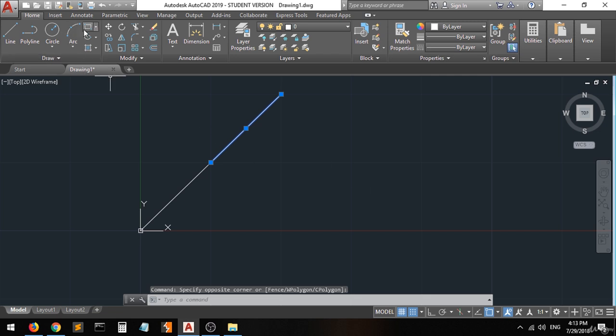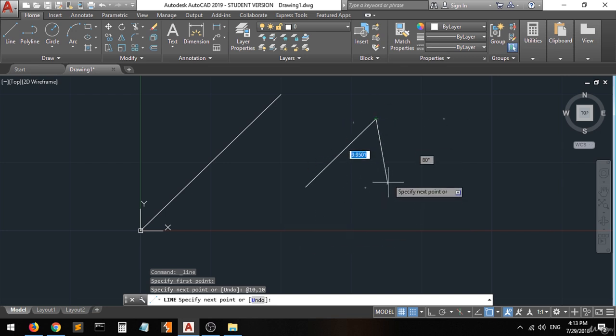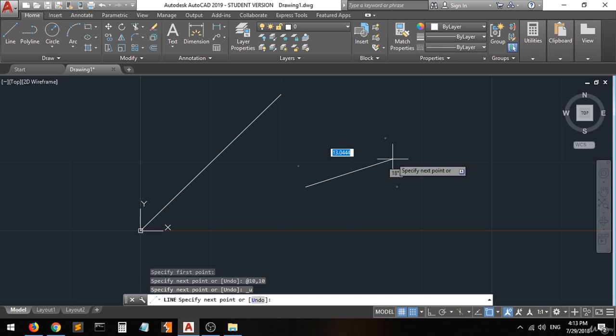So, for example, if we want to create a square, starting from this point, okay, I want it to be a 10 units square, okay? So we do this, we put it in here, we do what? The at sign, we go for 10, comma, 10, enter. Go to Control Z again. We want this line to be going to what?